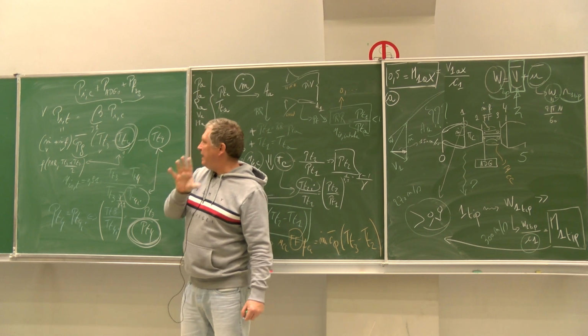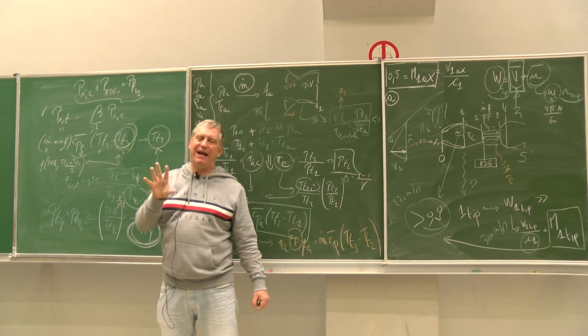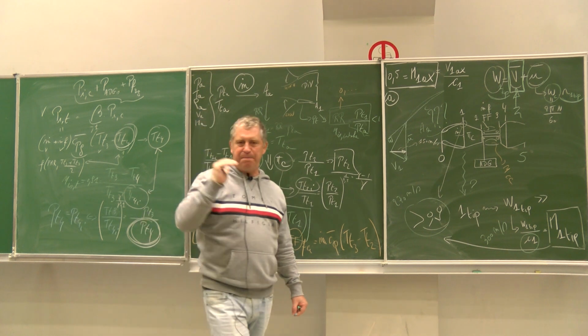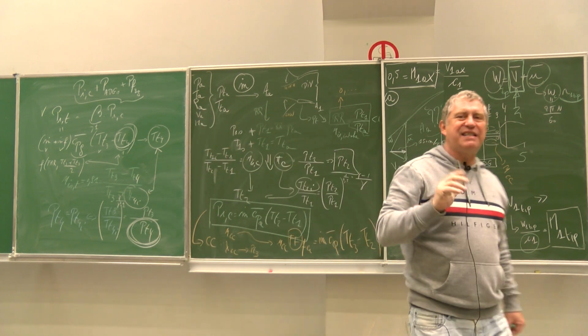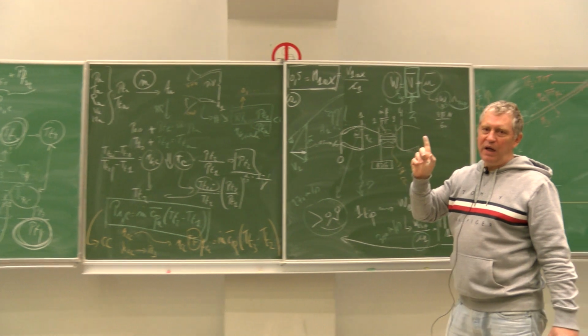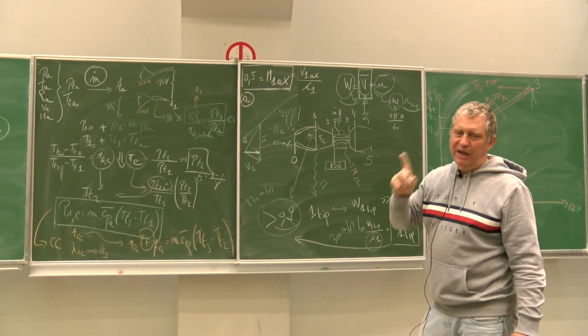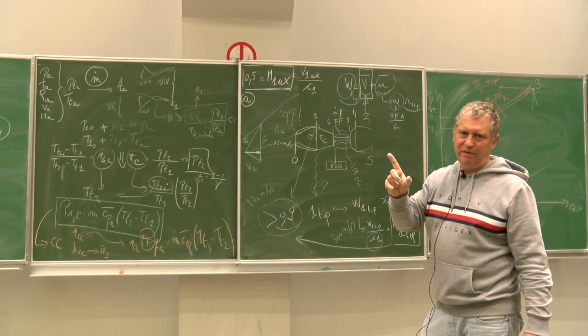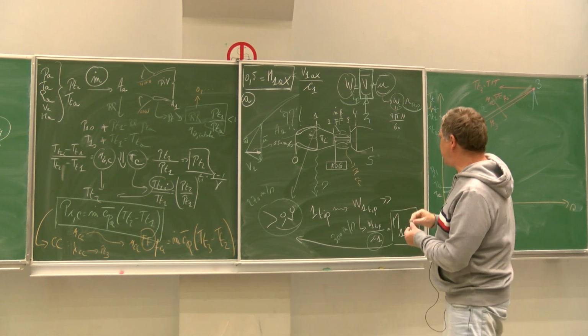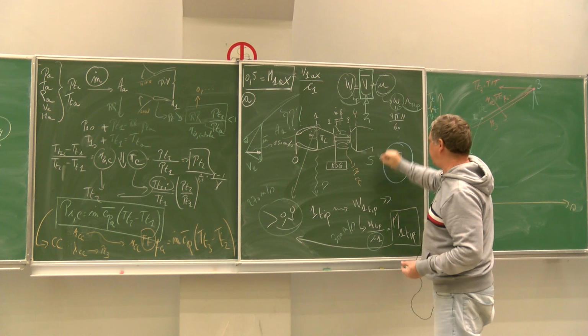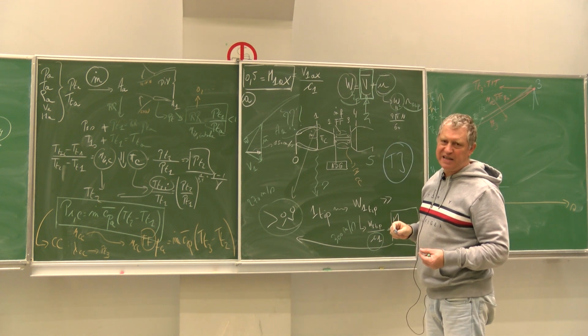The only load is, let's say, the compressor plus some accessories. So the expansion in the turbine is much lower than in the basic gas turbine cycle, much lower than in the turboshaft in this cycle. This cycle, I call that a turbojet. I have not yet mentioned this name.